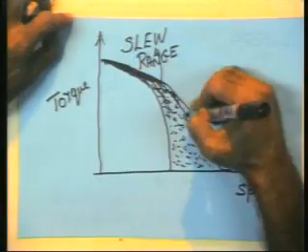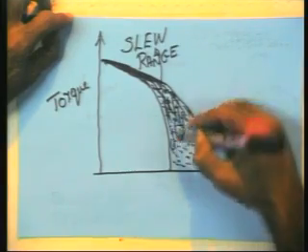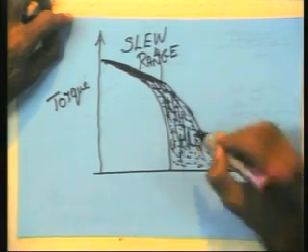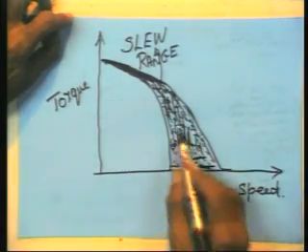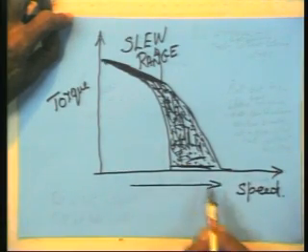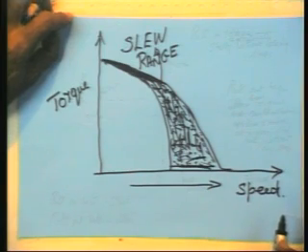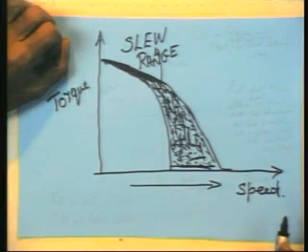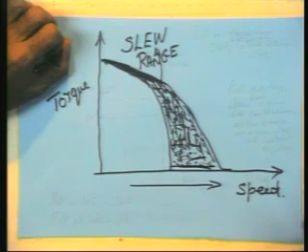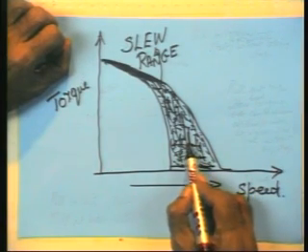All right, is that okay? Now let's see what happens. What is the meaning of all this? How does it affect us? I just darken this a little more, the slew range. In the slew range, where the switching is higher, as the speed is increasing, the torque is poor. Consequently, you can only overcome the friction torque. It cannot accelerate and decelerate with ease in this.